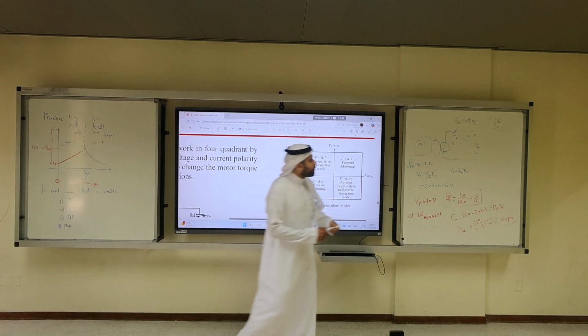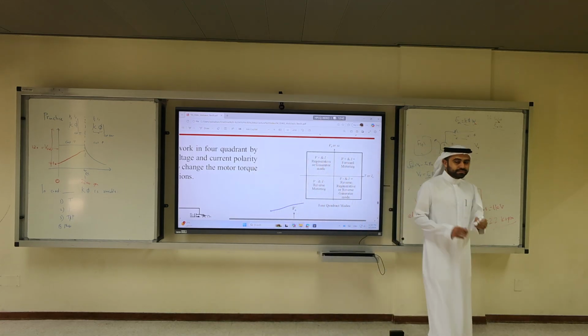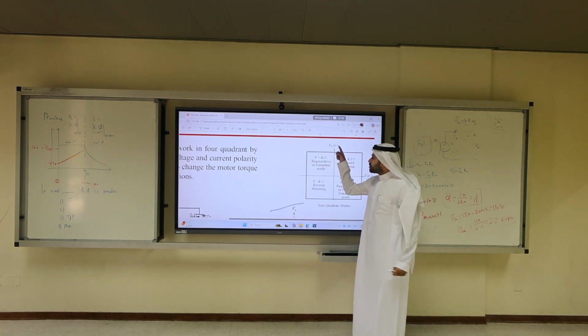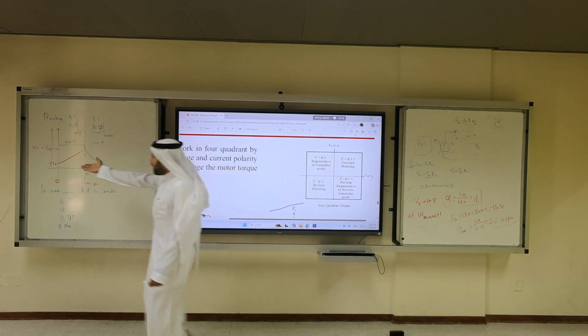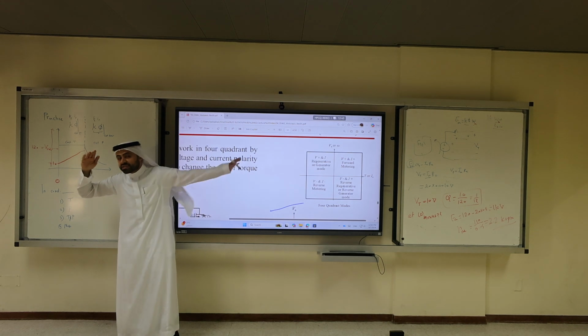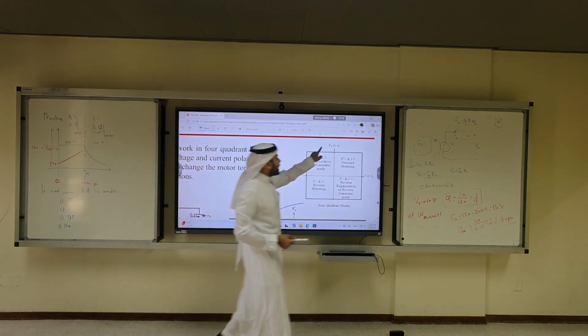And what's the formula of armature voltage? K phi times omega. So it's proportional to omega. If I increase VA, I increase omega. You increase EA, or in this figure it's called EA.